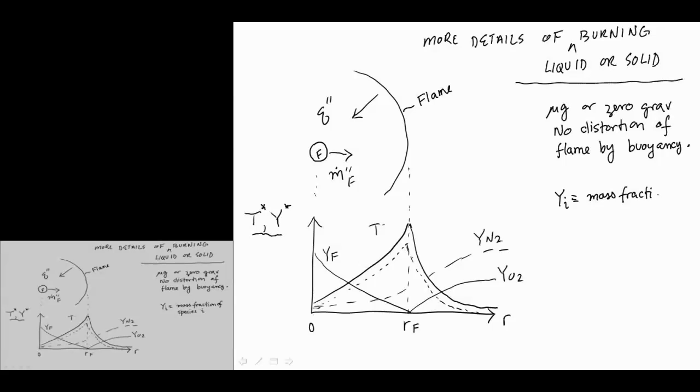What we would see is that we've already talked about the fact that it's the interplay of the heat flux that generates the mass flux that controls the burning. So we've already said that. But what we would see is that there is a mass fraction of fuel at the interface, at the droplet interface. Inside, it's a single component droplet, and then there's some mass fraction beyond that.